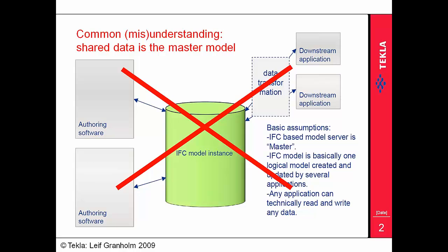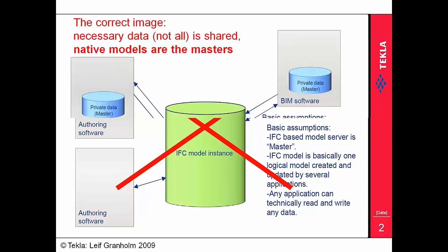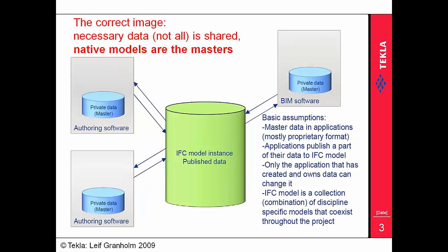That would be the case if the master model were the shared model. But in fact, the master models are the individual domain models, and then the IFC model is published for sharing purposes, so that other people can access the data that we have been producing in our proprietary models.